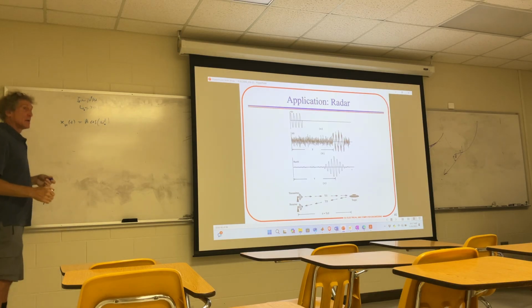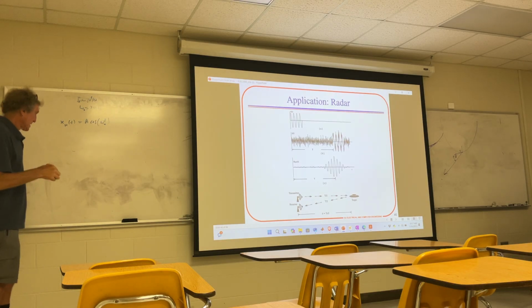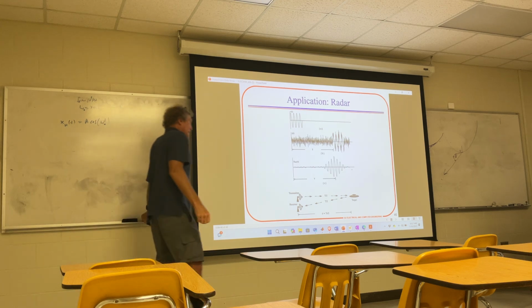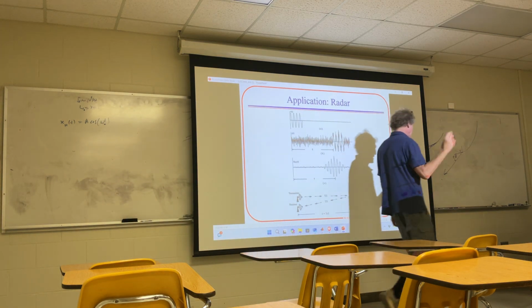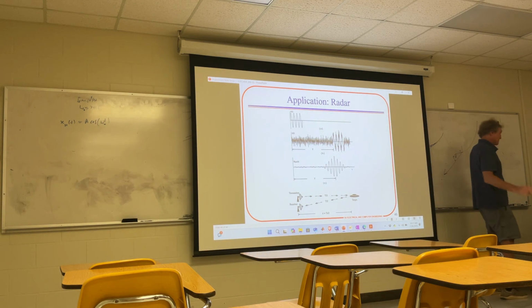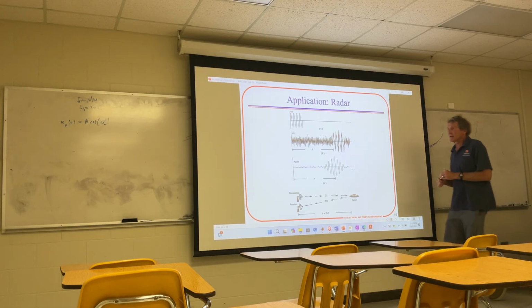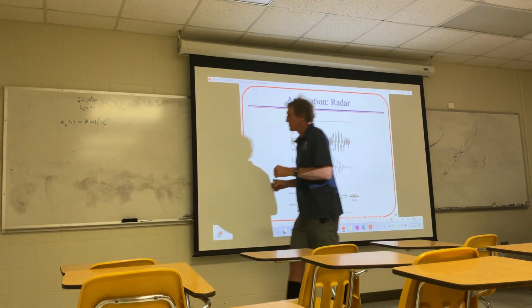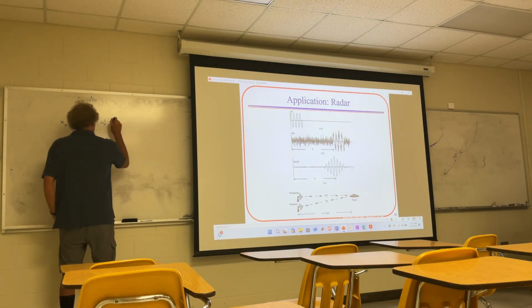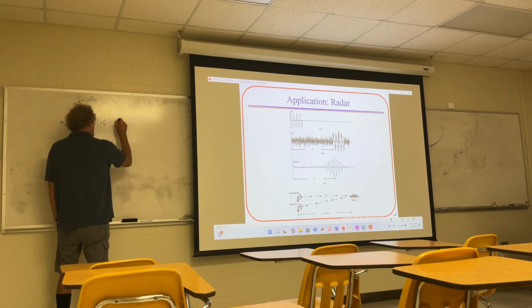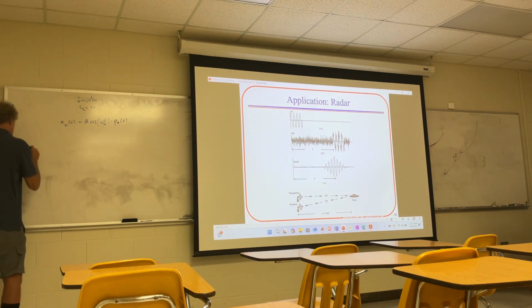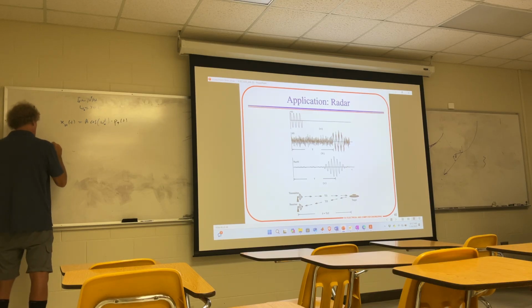So I have a constant high frequency, and now I want to make only a small portion of that actually created and launched. Mathematically, we multiply it by a pulse function, p tau of t, which is basically the rect function with argument t over tau.